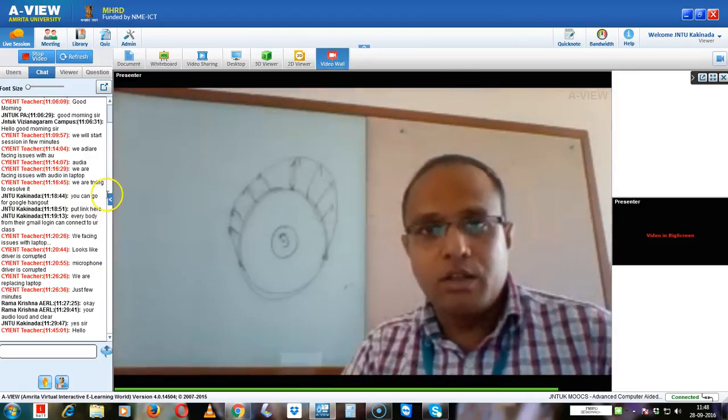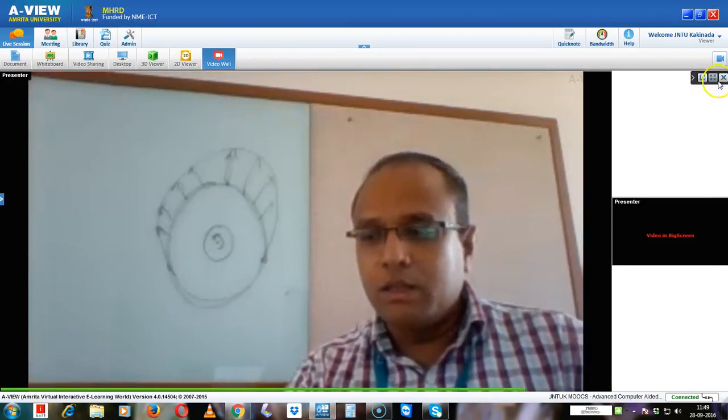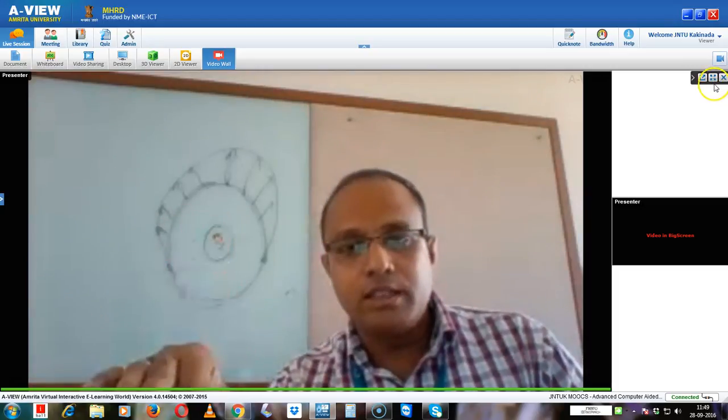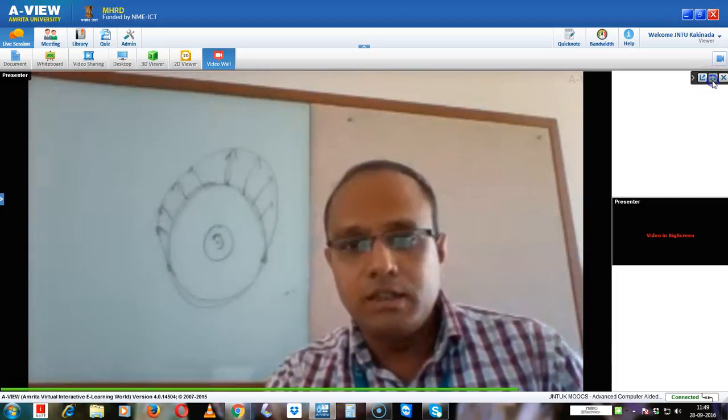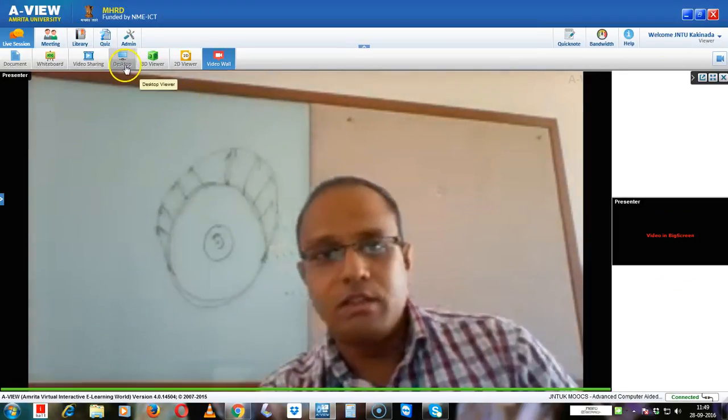In most aero engine applications, disks are subjected to uniform loading throughout the 360 degrees, and since blades will be there, we take a simple sector model. So for this problem, the disk is subjected to an angular velocity of 1000 rpm. A simple cyclic sector is sufficient.